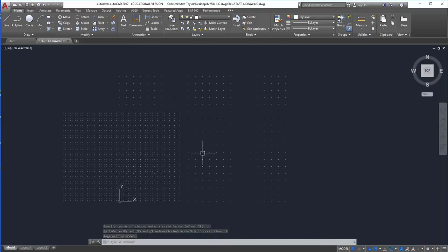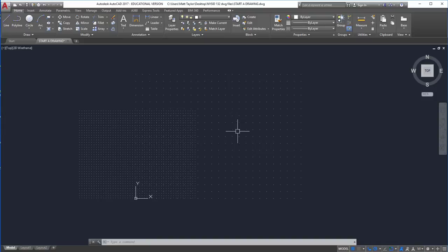Now here's that glitch I was talking about before. For some reason these days, AutoCAD shows these two different grids. This is the one we want. And just look at that for a second. That's a grid. If you counted these, there'd be 24 spaces left to right, starting at the origin, going to the right, and 18 spaces coming from the x-axis upward. So 18 inches in the y direction.